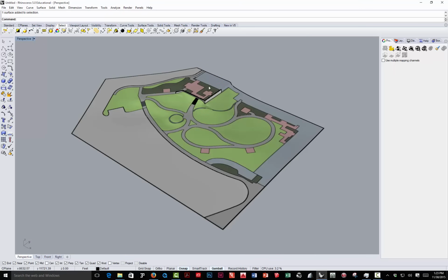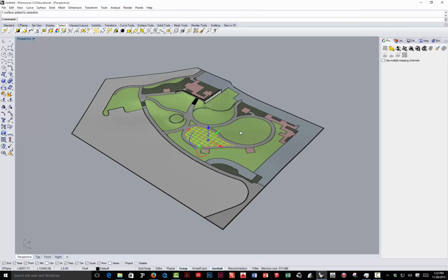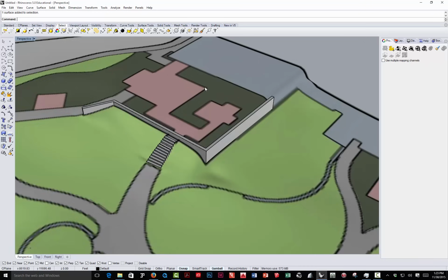And now I have all these separate areas that I can apply different textures to, and even right down to the road and the curb, and everything works pretty well. So Rhino is really good at splitting things apart and not having little pieces. That's one of the things, the drape command in SketchUp works pretty good, but it's about 98%. There's still always a couple percent that it just doesn't do. Rhino seems to be really good at doing that.